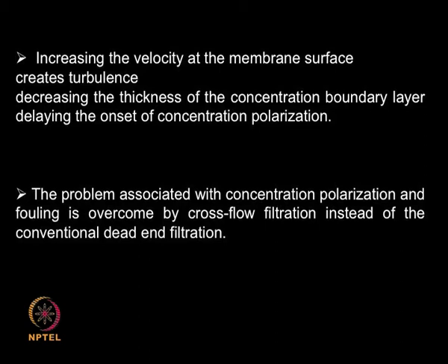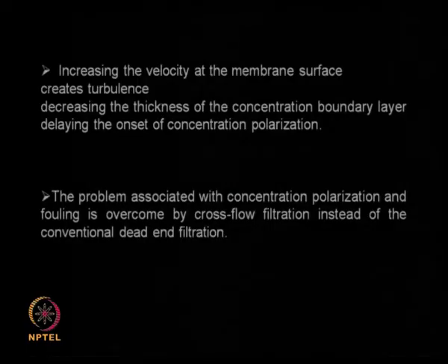Another way by which you can reduce the concentration polarization is using cross flow filtration. So far what we saw is a perpendicular flow, that means the flow is perpendicular to the membrane surface, or the membrane surface is perpendicular to the flow direction. That is also called dead end filtration. So normal filtration is also called dead end or perpendicular filtration.